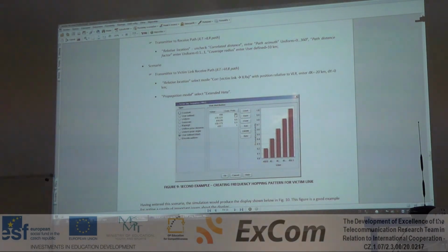Okay. Next channel will do exactly the same, also with 20%. But since this is a cumulative probability, we have to add the previous one. So here, for this channel, 125 kilohertz ahead, we have a cumulative probability of 0.4, and so on. So at the end, all these channels will be used with the same probability, 20%.